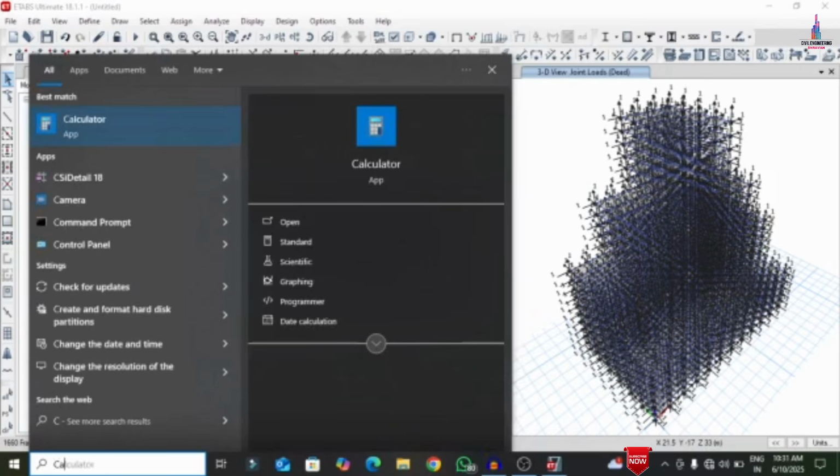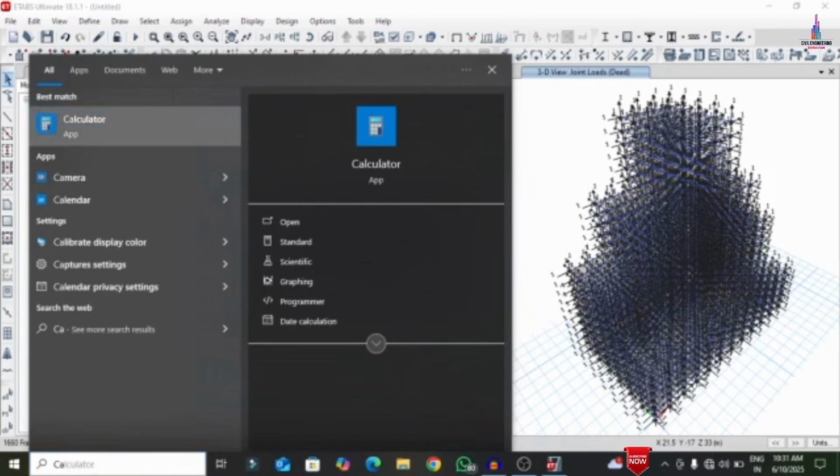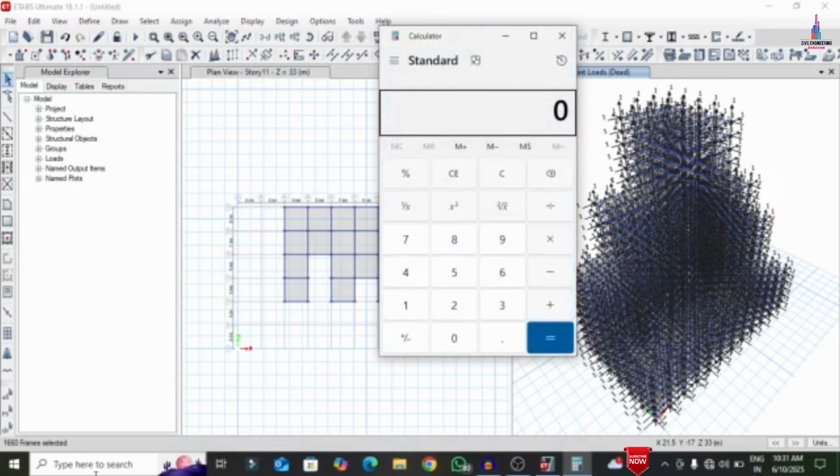I already calculated the wall loading condition system, which is the combination of external wall, internal wall as well as the parapet wall, in plenty of the videos, but once again I will calculate. So here I am assuming external wall will consist of 0.23 thickness. Height will be approximately 3 meter. I am multiplying this value with 20 unit weight of the brickwork so that it will get the value of external wall as 13.8.